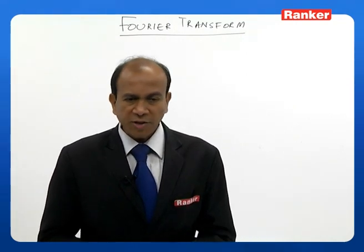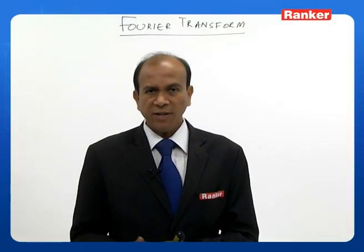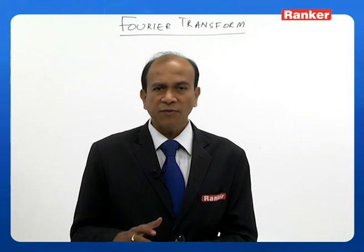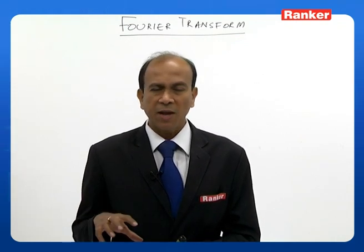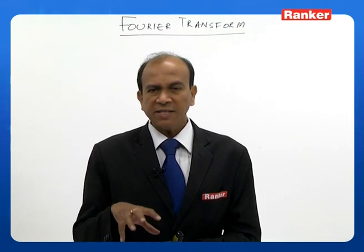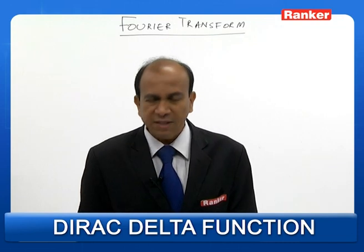So, what is autocorrelation? The autocorrelation process provides a measure of similarity between a signal and a replica of the signal delayed by a variable amount, and is a function of the delay variable. That means there is a function g of t and there is the same function g of t delayed by a certain variable tau, let us say. So, g of t minus tau. So the autocorrelation function is defined with respect to the delay variable, that is tau. Let us see the formula.